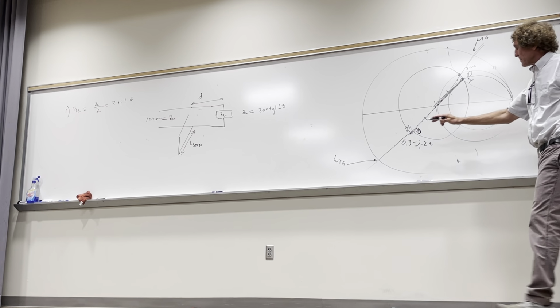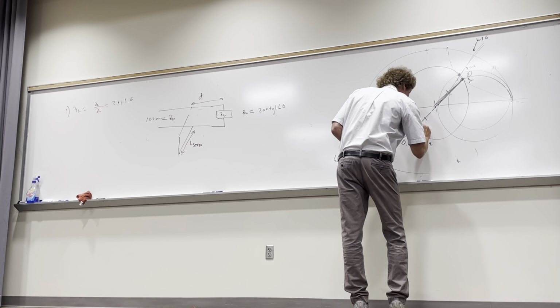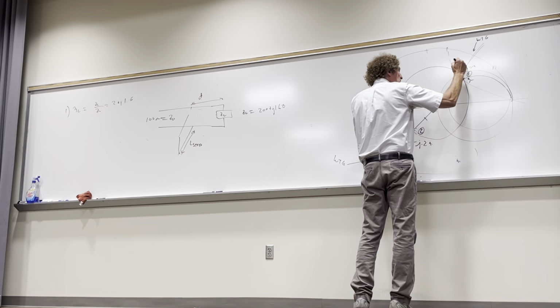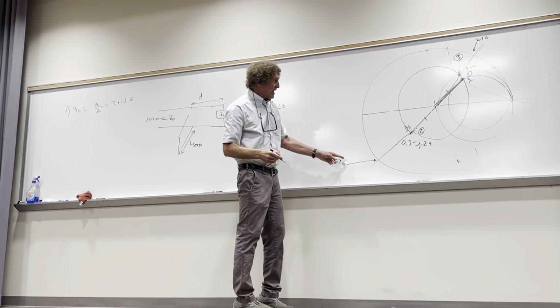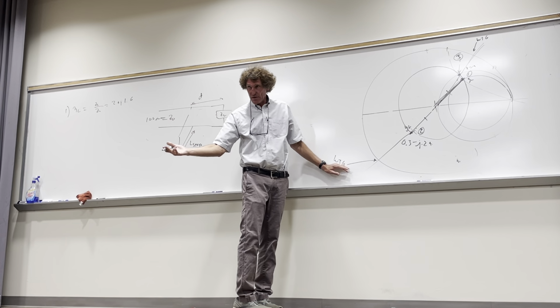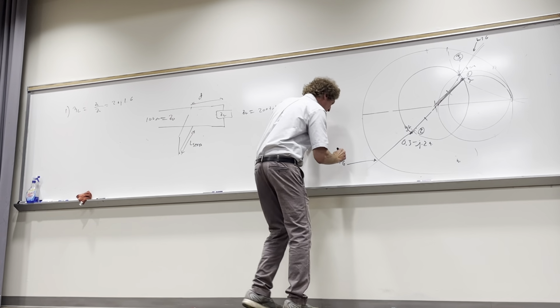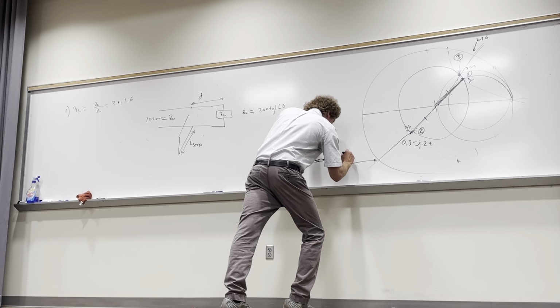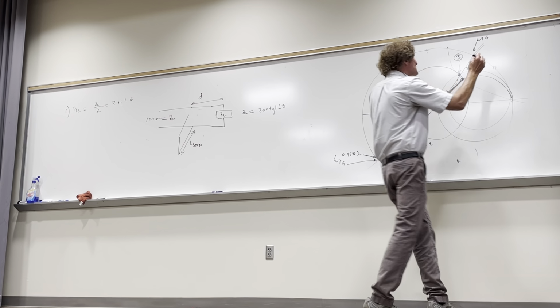All right, we would move from here, and this is 0.2. Then we'd move to here, this point, very close here. This would be 0.3. And then whatever this value is, we take that value, subtract this value, and add a half wavelength. Do you all remember doing this, class? By the way, does anybody have this value? 0.458 wavelengths. 0.458 lambda right here.